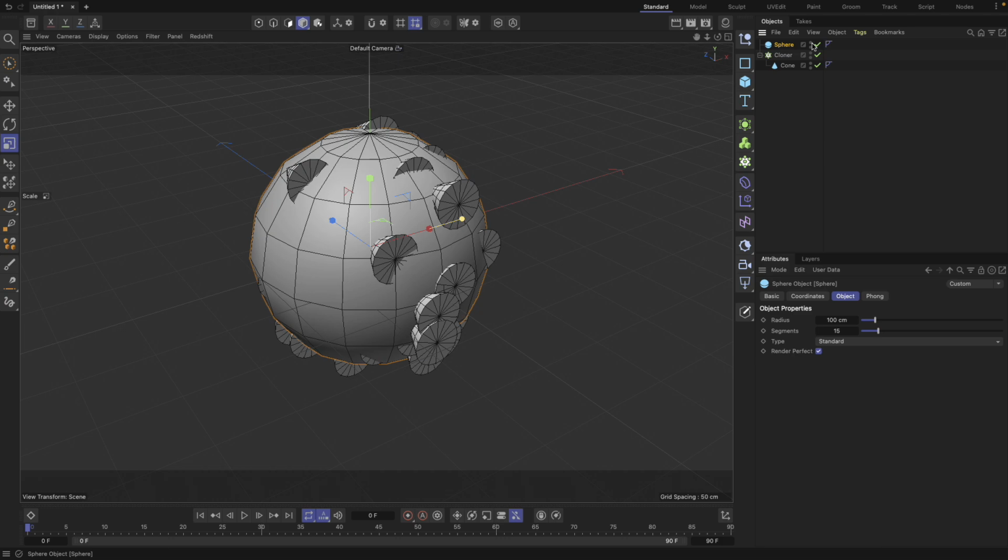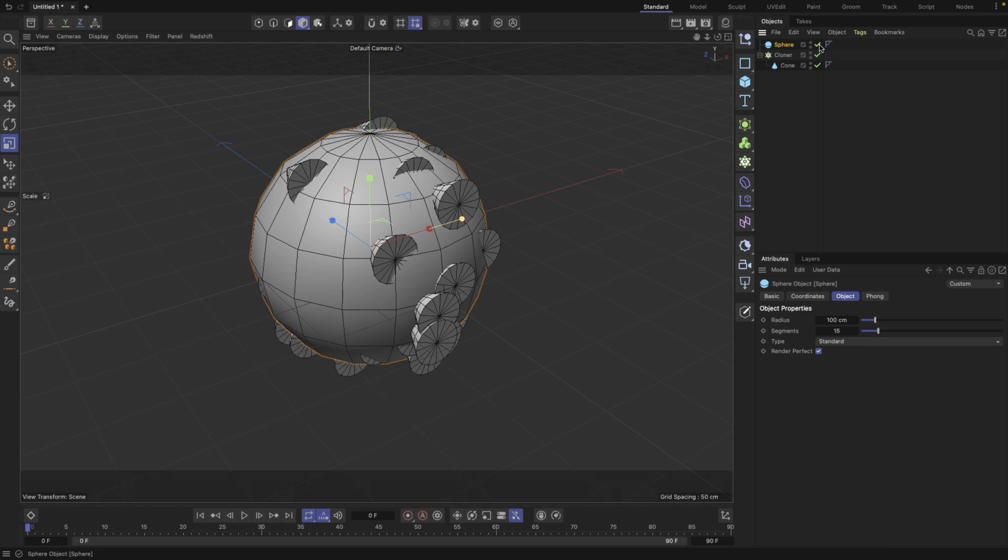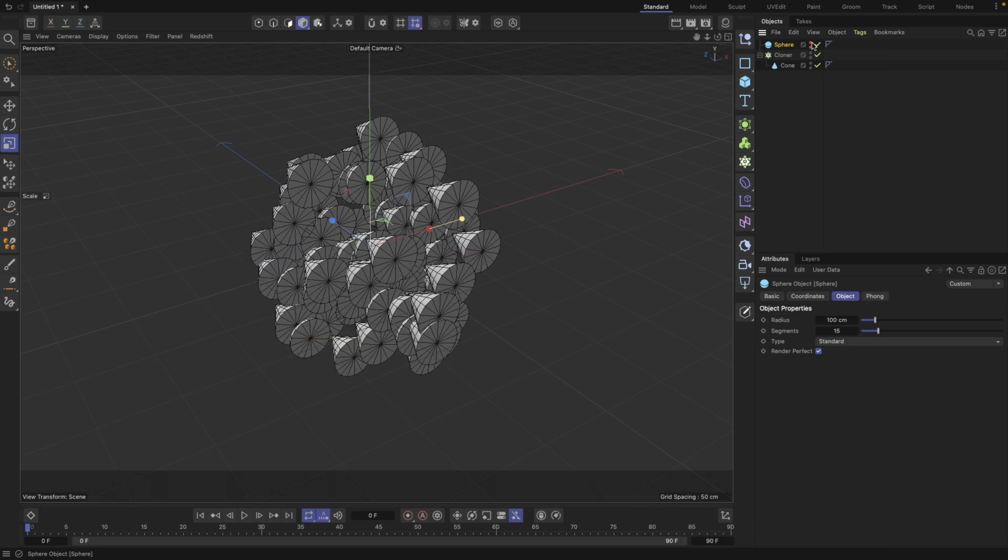By the way, there's a difference between these two buttons. I haven't shown you these two small dots. This green, red dot that is next to each object. So the difference between these and this check mark here is like this check mark disables or enables the object, while this dot here hides or shows the object.